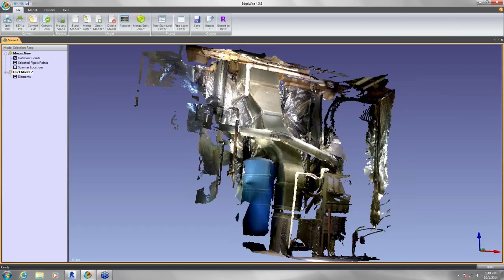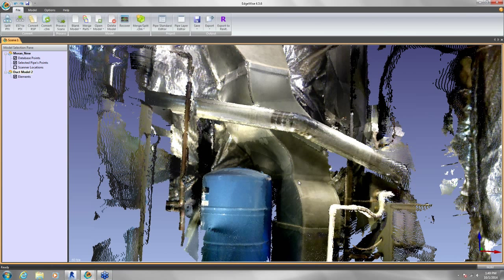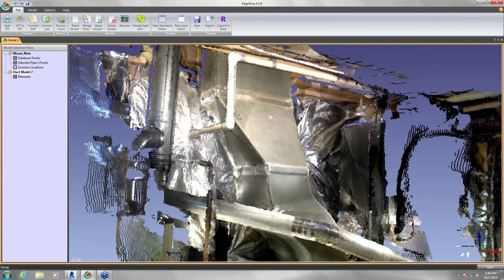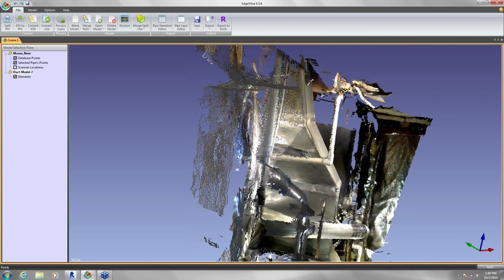But there's a straight piece of duct right here as it connects to the blower box, and from there on out, there's a little... This isn't even a Revit item that can be brought into Revit. It's some kind of a round transition, which we'll model as something that can be read into Revit. Then it goes into this S transition, which I'll model as two elbows to get it into Revit. There's a strange homemade transition up here, and then if I rotate it here, you can see that even this upper part that kind of looks like it ought to be straight is not. It's yet another transition.